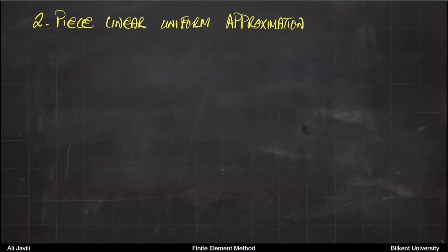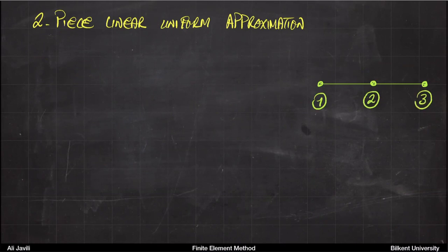And then again, what we want to do, or let's say that first step to approach this problem, is to properly write the shape functions. So again, let's say this is the domain, and maybe this is 0. Let's say this is the last point. Okay, this is the point in the middle. So this would be node 1, node 2, node 3. Coordinate wise, let's say this is at coordinate 0, this is at coordinate 0.5, and this is at coordinate 1.